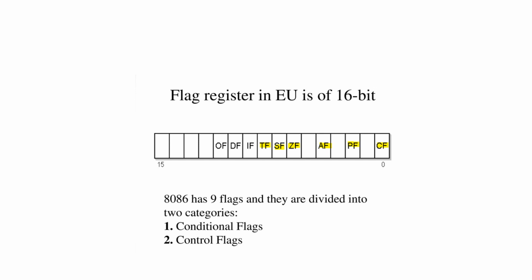So in order to run a program in single execution without any interrupt, any other interrupt should not disturb the processor. For that, if I make this 1, or if the trap signal has come, this will be 1. So that's why the other signals will not disturb this. So it has the highest priority.